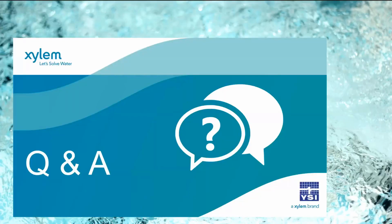Thank you, John. Next question. Can we relate TOC measurements with BOD or use TOC values to estimate BOD? Yes, you can. However, what that does require, let me just back up with the answer again. There are provisions within US EPA regulations that allow for the substitution of BOD with TOC.